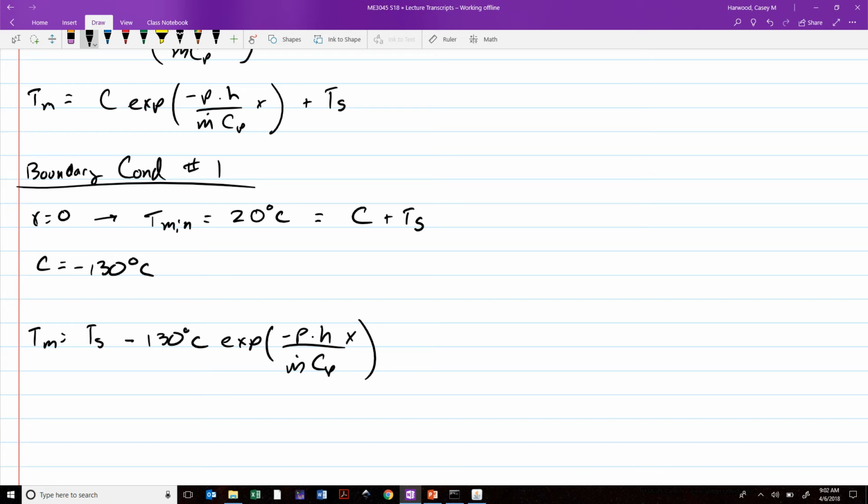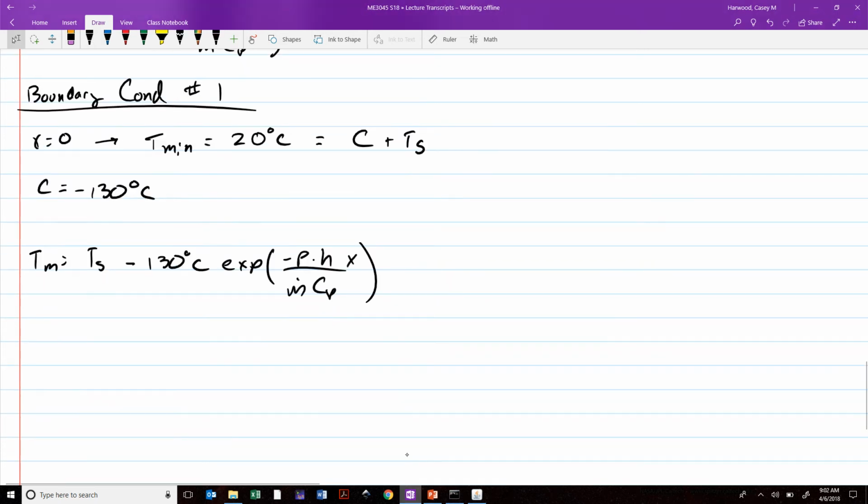The way we would do it, let's say we're all seeing omniscient beings, would be to define a reference temperature that is T in plus T out over 2, the average of the mean temperatures at the inlet and outlet, halfway through that process of heating up. Seems like a pretty reasonable approach, right? The issue is we don't know T out yet. Okay, that's what we're looking for. So our approach to the problem hinges on the solution to the problem. And there's no way of getting around that.